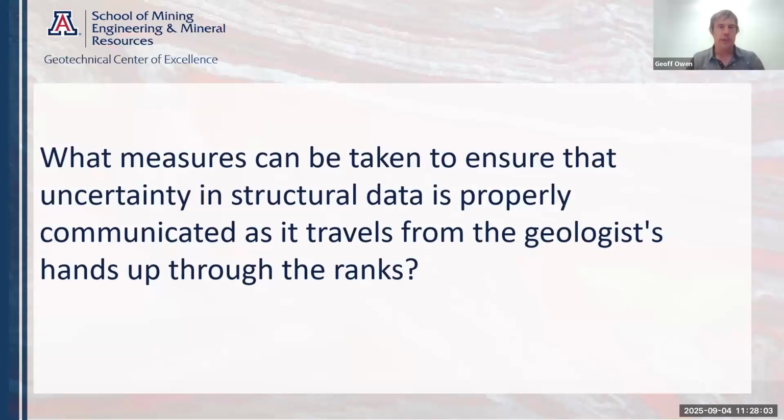If we're going into an area and you're creating wireframes in an operational environment for geotechs, if you don't have a lot of data for a certain area, I find there's this constant conversation where a geotechnical engineer will say, can you please put a structure in there, even though there isn't much data, just so we can plan for some sort of uncertainty or scenario. But then I've also seen that if we do put a wireframe in there, it sometimes becomes truth. And then all of a sudden, again, you're modifying haul roads and plans.